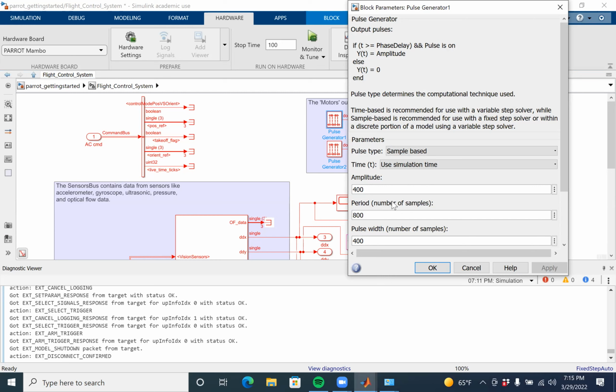And for this pulse width modulation, you have control over amplitude, period, and pulse width. So you can vary the pulse width, and that will change the speed of the motors. And the pulse width, which is over here, would be the input from your theta angle and phi angle. Everyone understood this? And that is how you would actually control the roll and pitch.